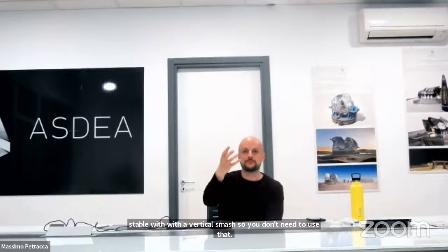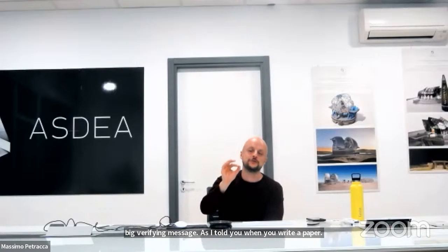Yeah, also because this material seems to be pretty stable with a very coarse mesh. So you don't need to use a very fine mesh. As I told you, when you write a paper, it's better to have a very fine mesh because you obtain nicer pictures of a more detailed crack. But in this case, you can see that the results are basically the same. With the crack plot, you still can obtain beautiful pictures. But in 1 minute, you have the cyclic analysis super fast.